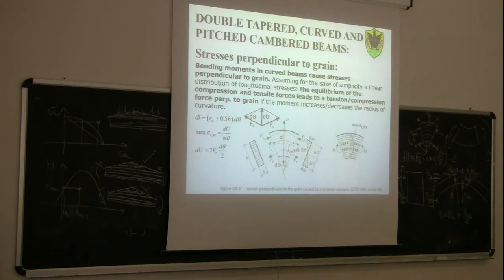If you replace this expression within the one before, and if we now remember that FC and FT can be calculated using the Navier formula, so it's basically 1/4 of sigma N times b times h, where sigma N is the maximum bending stress. Because of course the area of this triangle is sigma N times h divided by 2.